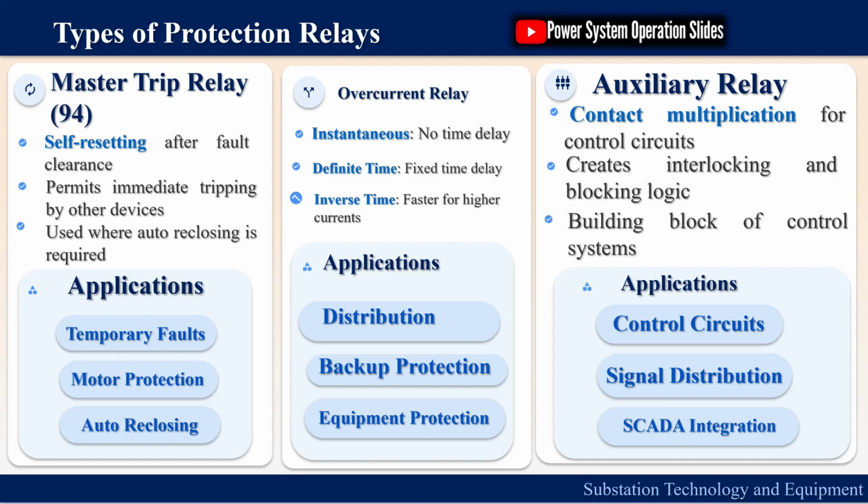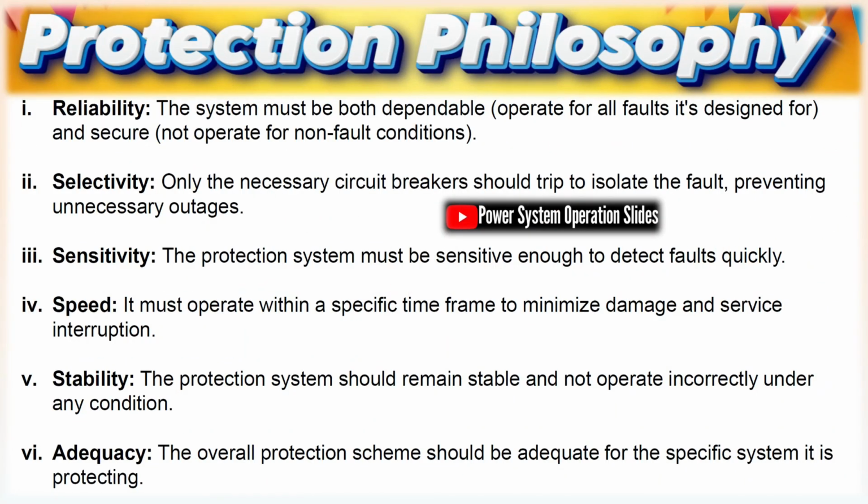Ring/mesh bus. Circuits connect in a closed loop, allowing feeding from 2 directions. Requires directional protection and is difficult to expand. Supports high continuity with limited scalability.